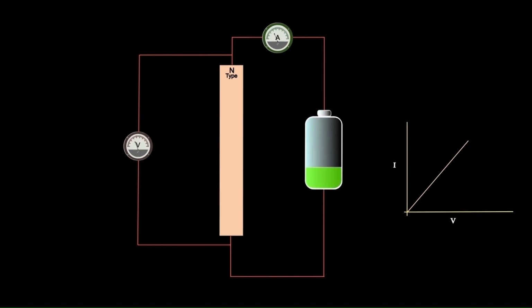By changing the amount of N-type dopant, we can control the resistance at the time of manufacture. Such a structure is not useful as a circuit element because a standard off-the-shelf resistor is much easier to make and therefore cheaper. If we put a layer of P-type semiconductor on the top and bottom of the central piece